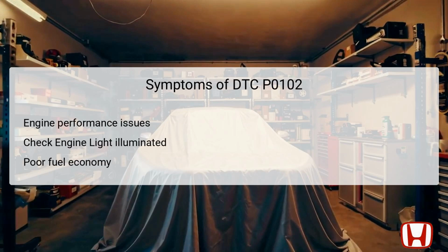The symptoms that accompany DTC P0102 can significantly affect vehicle operation. The most visible sign is the illumination of the check engine light on the dashboard, alerting the driver to a potential issue. Performance-wise, the engine may exhibit hesitation, stalling, or irregular acceleration, greatly impacting driving experience.